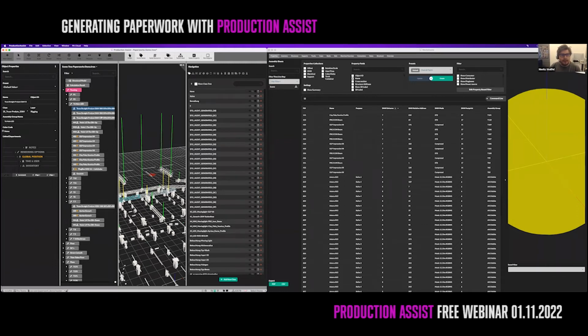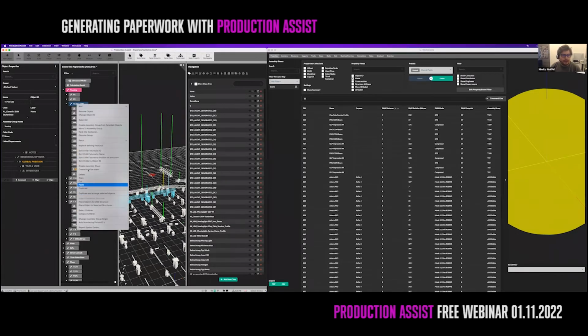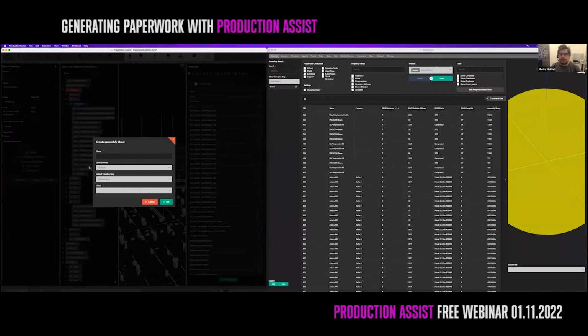So for the main LED truss, I want to tell the people who assemble this how this is actually plugged onsite into the plug boxes. For this, we have something that we call an assembly sheet. If I'm right-clicking this assembly group and use the command create assembly sheet, it allows me to create an assembly sheet which just contains the objects that are inside this group. When you change what's inside the group later, the paperwork automatically gets updated for this.